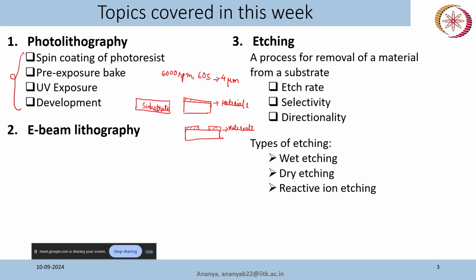Now a few of my substrates were like this one, bare silicon substrate, and a few were like this third option that I am showing you. So this is 1, 2 and 3. A few were patterned, and the sizes of this pattern were not very thick, so I am hoping that I was able to get an even coat of photoresist on top of this kind of patterned substrate. So this is the first step in a photolithography process.